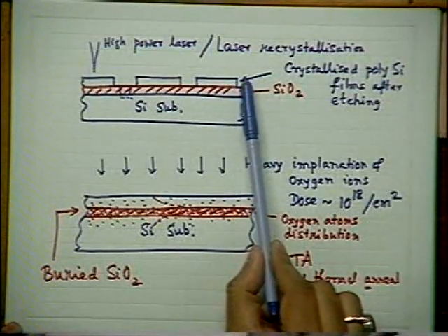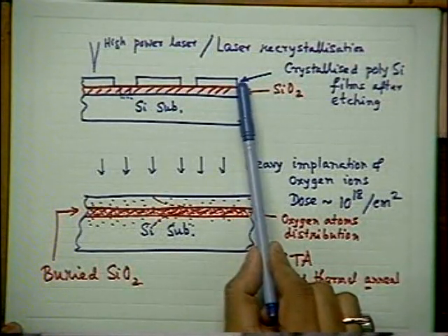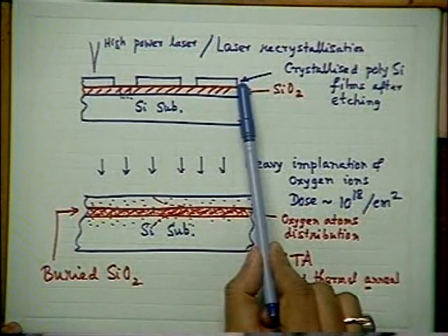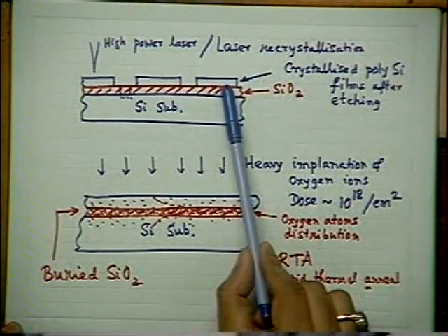So what people do for polysilicon growth, normally the temperature is around 750 degrees centigrade. Whereas for epitaxial growth from silane, the temperature is typically 1050 degrees centigrade. There are other alternative sources like silicon tetrachloride, SiCl4, dichlorosilane, SiH2Cl2, etc. So these are the technical details. Many things are there, and I don't think there is much scope to teach them in detail.